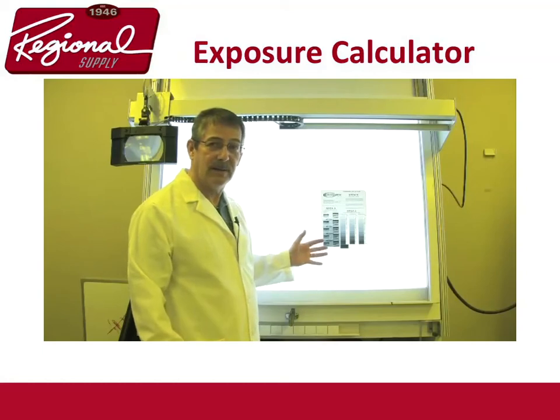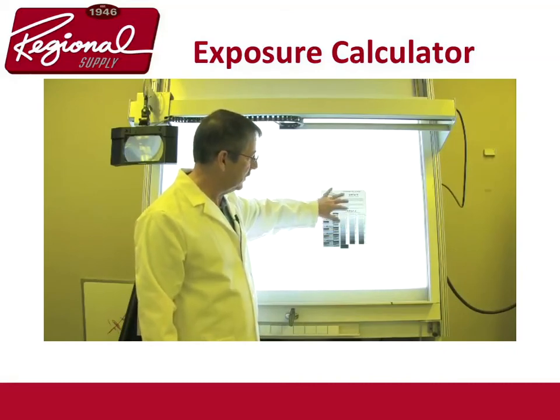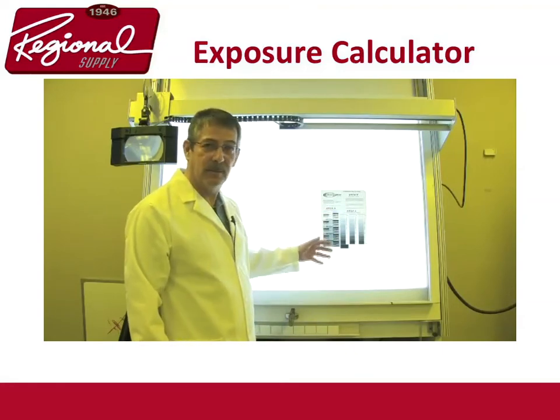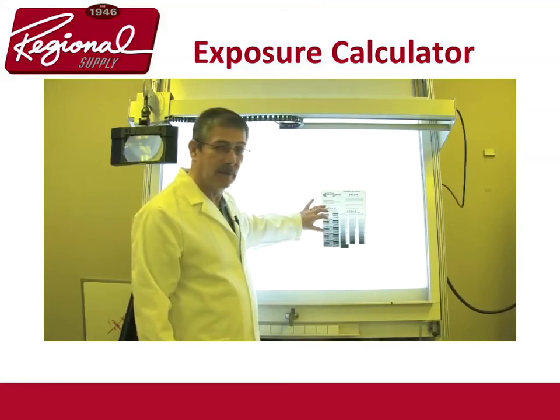Now, once you get all that done, the next important thing to look at is area B and C. These areas are for resolution, to see if you can actually hold these areas with the mesh count you've got. That's really all there is to it. It may seem simple, but the fact is this little tool is a very, very powerful one. If you use it properly, guaranteed you'll have good stencils.